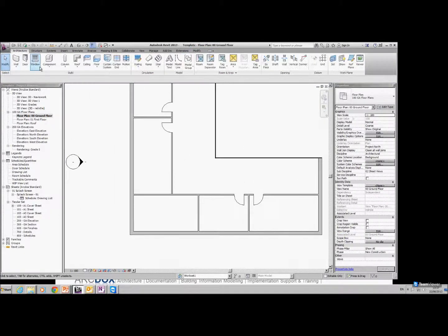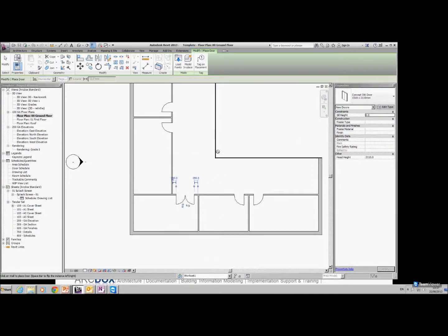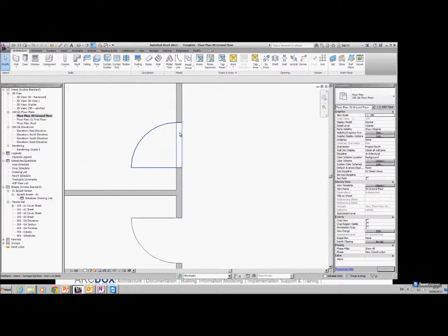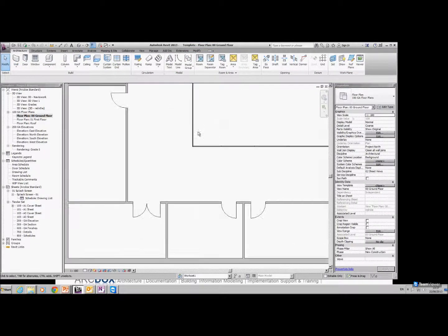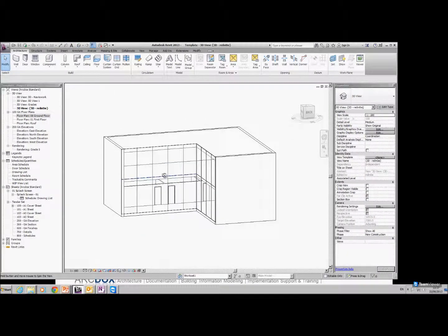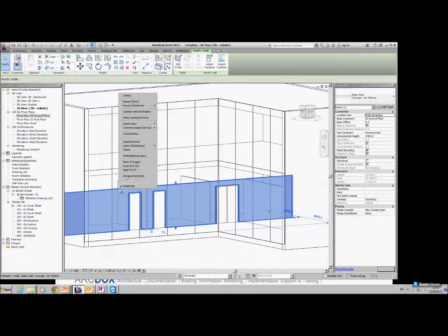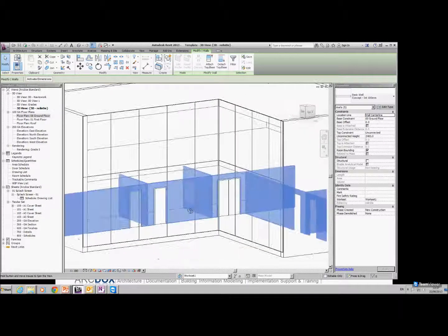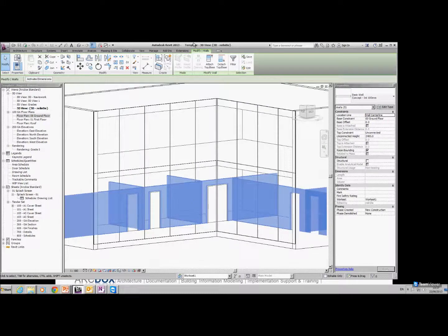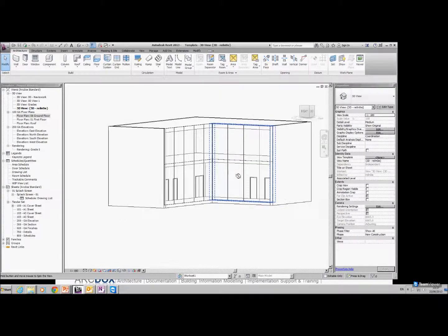So I'm going to just throw in a double door as well. Here, in, and let me see. Right, I think that's fine. I'm going to go back into my 3D view, and you can see the walls are not actually attached to the underside of this. So I'm going to right click, select all instances in entire project. I know they're just on here. So select them, click attach top to, and this, and now they're all attached to the top of that. And that's what I want.